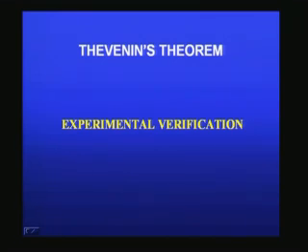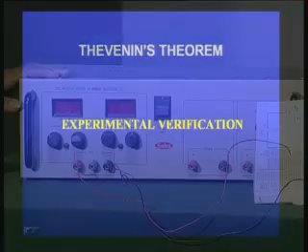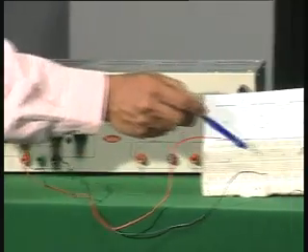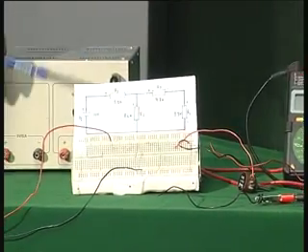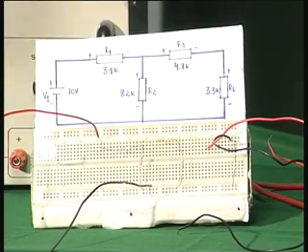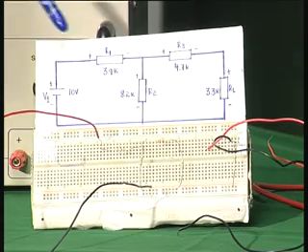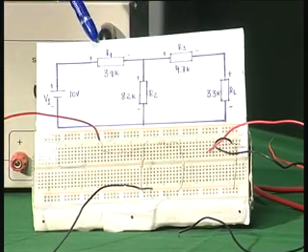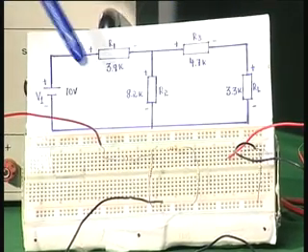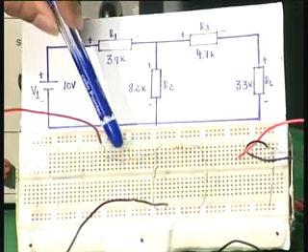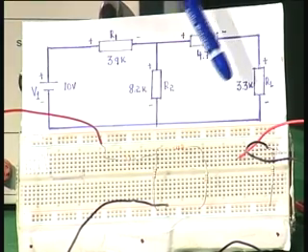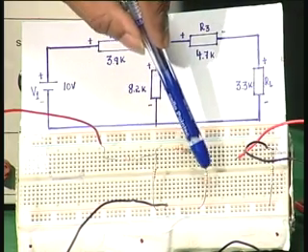So here I have the power supply. The power supply red and black lines are connected to this circuit, which for simplicity I have shown here. You have the same circuit which I just now did. This is the voltage supply V1, 10 volts, we will set it up here, and 3 resistors: R1 3.9 K, R2 8.2 K and R3 4.7 K. The same resistors are shown here. This is R1, this is R2 and this is R3, and this is the load resistance which is 3.3 K.